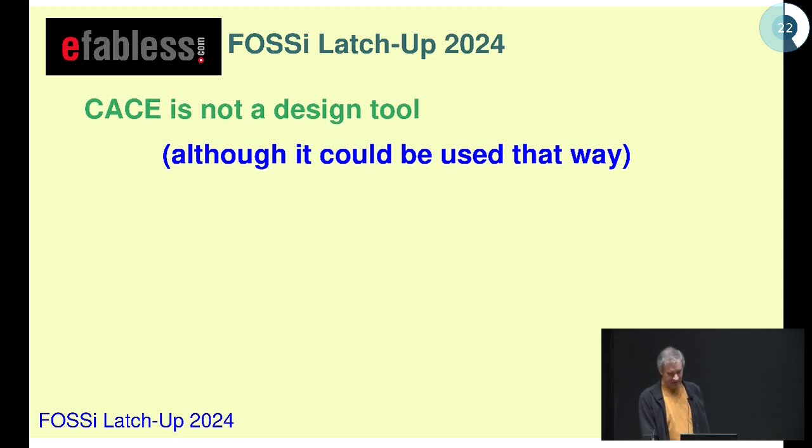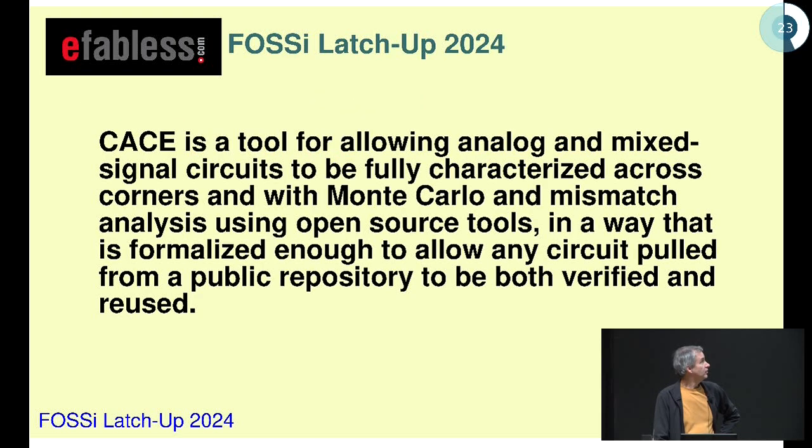So what is CACE exactly? Well, I did not intend it to be a design tool. I intended it for verification. It could potentially be used as a design tool. If I wanted to describe it, I'd say it's a tool for allowing analog and mixed signal circuits to be fully characterized across corners and with Monte Carlo and mismatch analysis using open source tools, in a way that is formalized enough to allow any circuit pulled from a public repository to be both verified and reused.